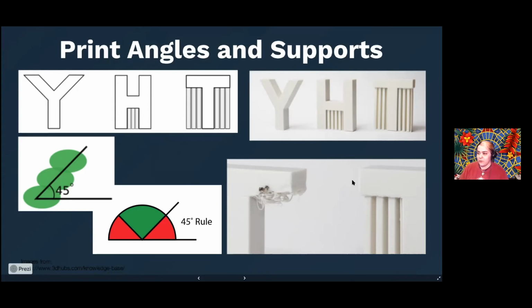Now there are some cool things you can get, like I said there were dual filament printers. You can get it so it prints that in a dissolvable material. I've seen where you can do that, stuff like that. Or you can have the supports that I showed with the other program, Mesh Mixer. It has these they're called tree supports. So they just kind of crawl up here, and then right about here, they'll break away and hold on to it.